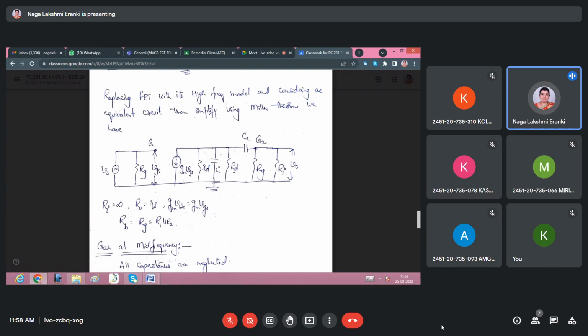So RD is the resistance which is connected between the drain and the supply voltage. From here is the output. In the next stage there is CC, the coupling capacitor. From the coupling capacitor, RI is connected. We are considering that value as RI, in parallel with RG. Why parallel with RG? Because in the next stage RG is in parallel with RI, so we are considering RI parallel with RG. The same in case of